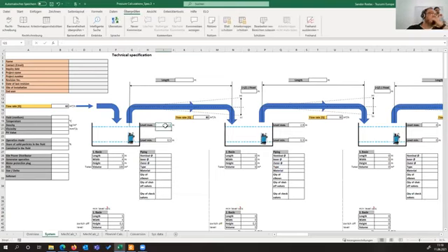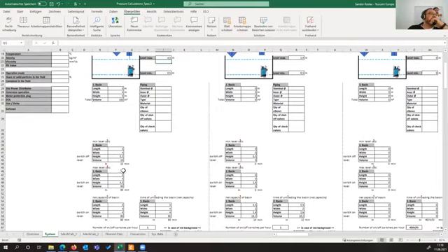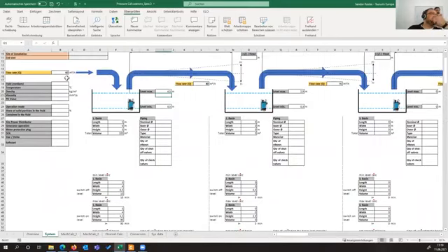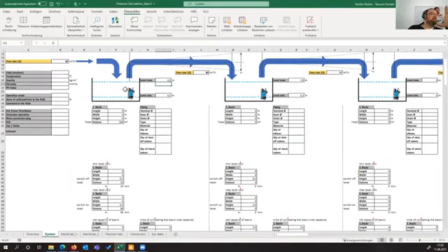So that system will immediately calculate the time you need to reach the minimum level at 60 cubic meter per hour inlet in the basin. Under this condition, 90 minutes will be needed to reach the maximum level.